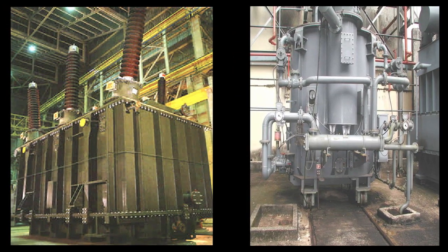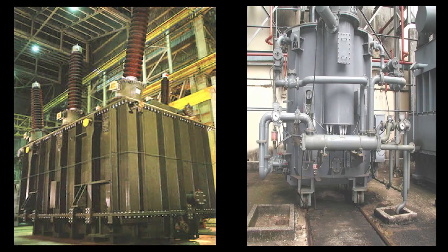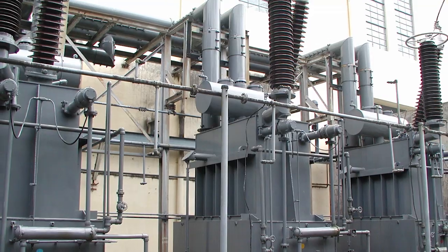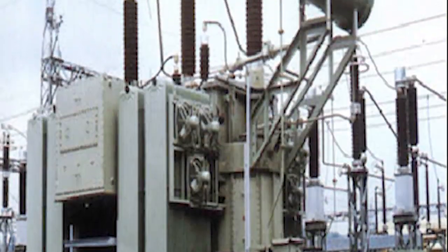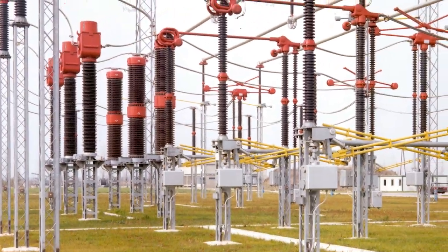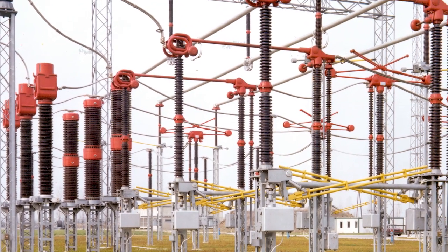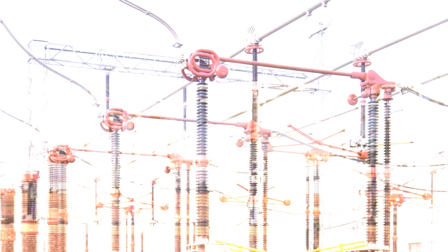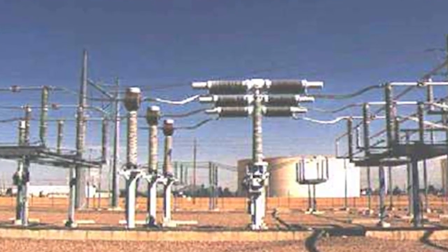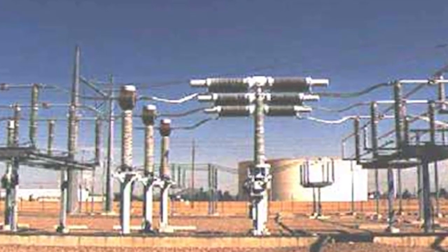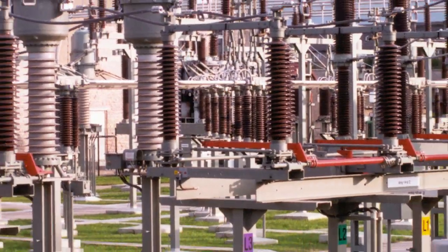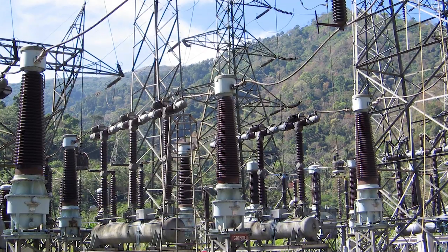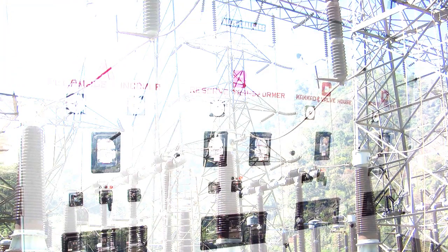Generator transformer is the electrical device that increases generator output voltage to match the voltage level of the transmission line. Switch yard. The power generated by the generating units is pooled in the switch yard and transmitted to load points, circuit breakers, isolators, earth switch, etc. Isolators and circuit breakers are switches that connect and disconnect the generator to the power grid.